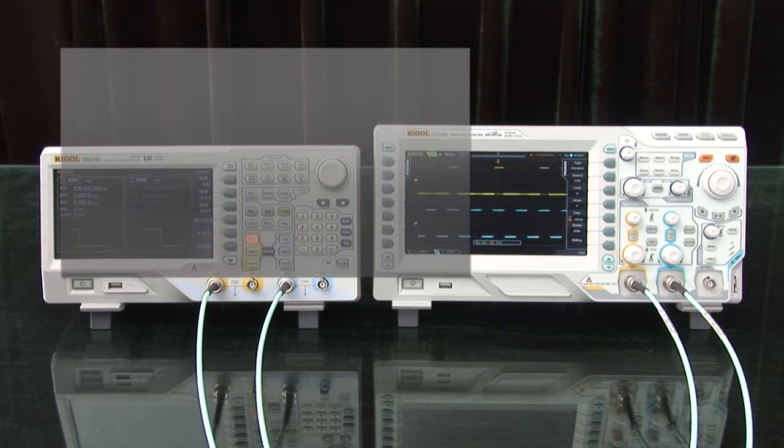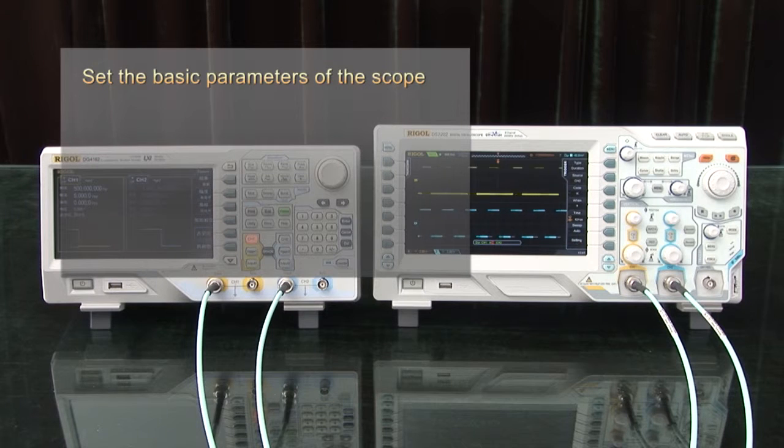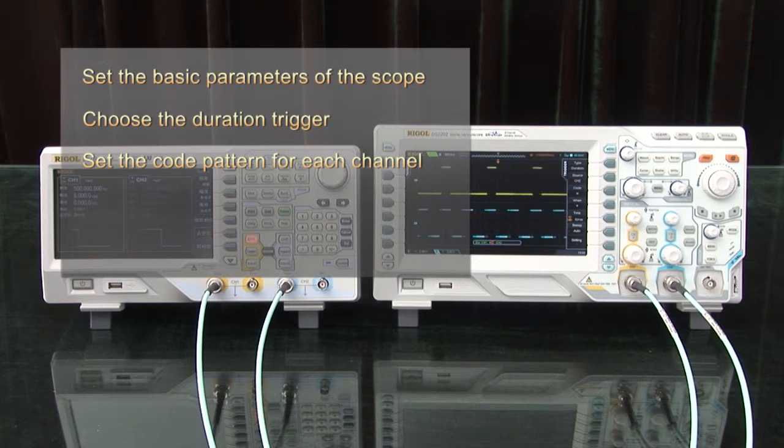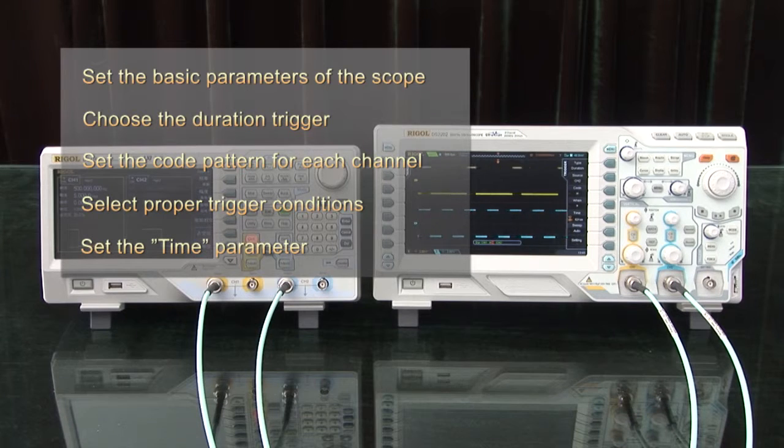The key points to remember: you want to set the basic parameters of the scope, choose the duration trigger, set the code pattern for each of the channels, select the proper trigger conditions for your input signal, and then set the time parameter.